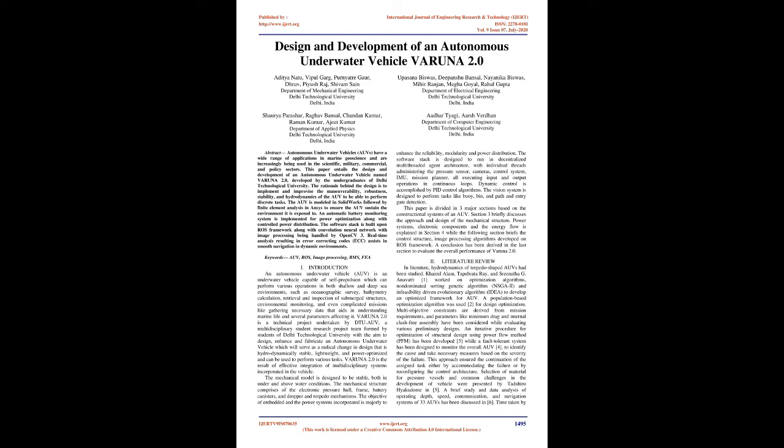The software stack is designed to run in a decentralized multi-threaded agent architecture, with individual threads administering the pressure sensor, cameras, control system, IMU, and mission planner, all executing input and output operations in continuous loops. Dynamic control is accomplished by PID control algorithms. The vision system is designed to perform tasks like buoy, bin, path, and entry gate detection.